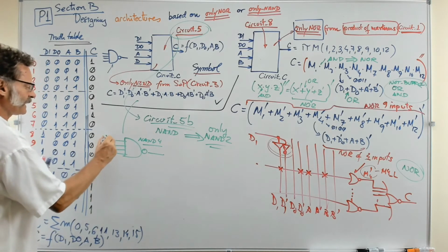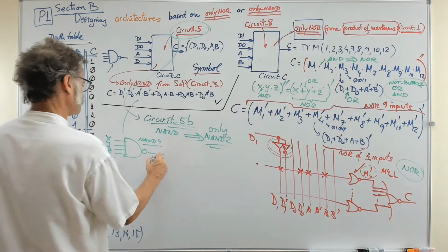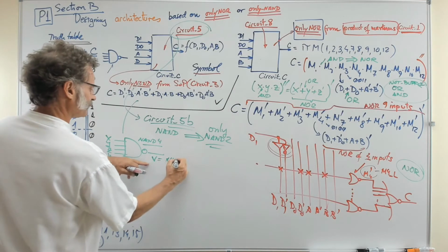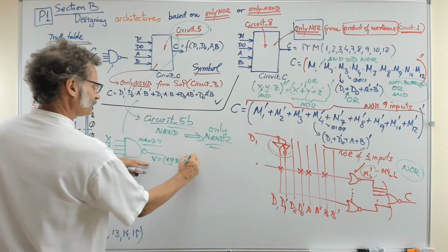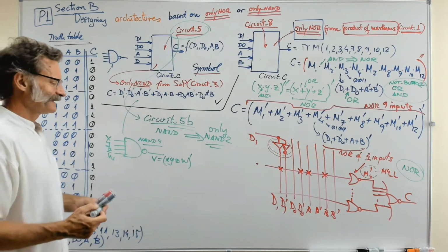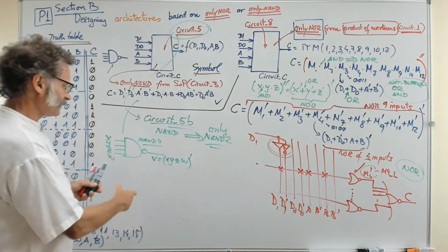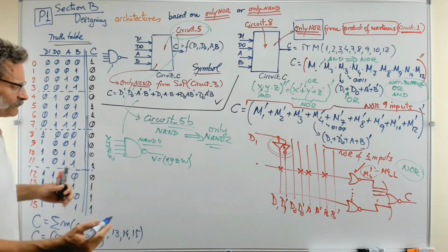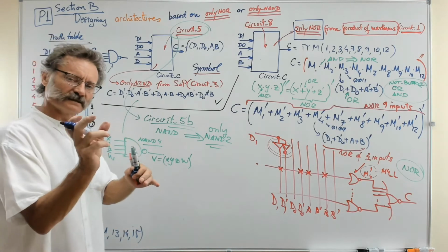Think of X, Y, Z, and W, and this is B. How can you invent this B, which is X, Y, Z, W, and a final NOT, in a way that this gate can be replaced by NAND 2? That's the problem to solve. This is not difficult because you only have to pay attention to grouping the inputs.